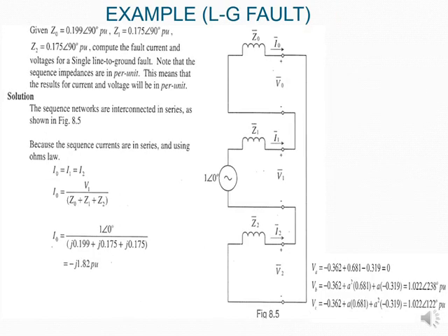So looking now at the next one, where they say they want us to calculate a line to ground fault. You've got exactly the same impedances that you've had before. Now in our formulas, we know that all our phase sequence currents are going to be equal, and that our V naught is equal to that V, which is really that one, not V1 necessarily, guys. It's that one at 0 degrees divided by the total of all your impedances. So you get what I naught is.